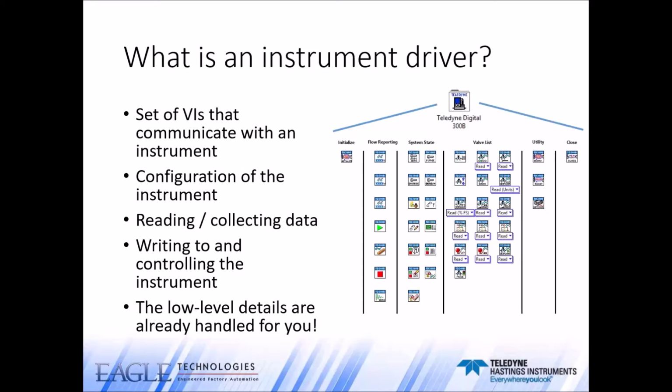Instrument drivers simplify instrument control and reduce LabVIEW program development time by eliminating the need to learn the programming protocol for each instrument. A LabVIEW driver converts the user commands in LabVIEW into instructions required for that device and sends them through a communication protocol like USB, serial, Wi-Fi, Ethernet, GPIB, to cite some examples.